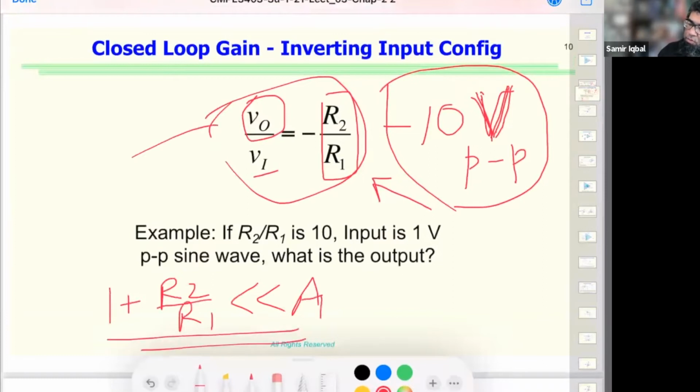So these two conditions have to be satisfied to control the closed loop gain, and to minimize the dependence of the gain on the open loop gain of the op amp. Are you with me so far? I'm sorry, it's a little bit crummy, but maybe I'll add more open pages going forward to have easy write up there.